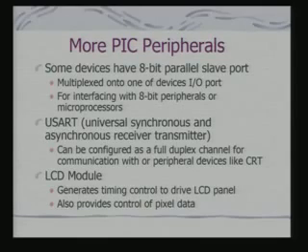It also has an LCD module. The LCD module requires what? A mechanism to do timing control for the purpose of display. So, it provides an interface for the timing control and also provides the control of actual pixel data, because whatever data is being written onto the pixel, how it is to be written, this pixel data would map to a memory area. So, that LCD module has provision for this timing control as well as management of pixel data.